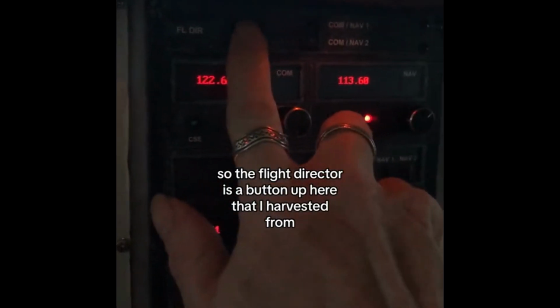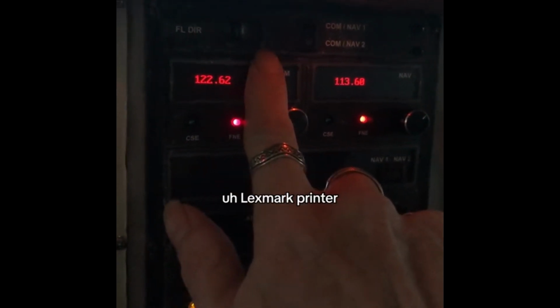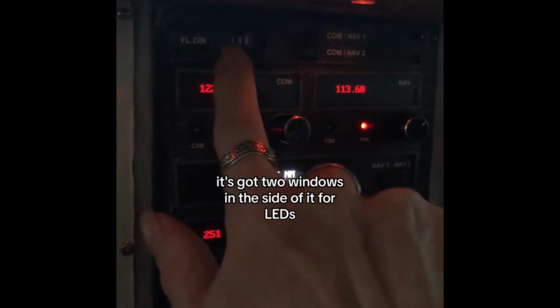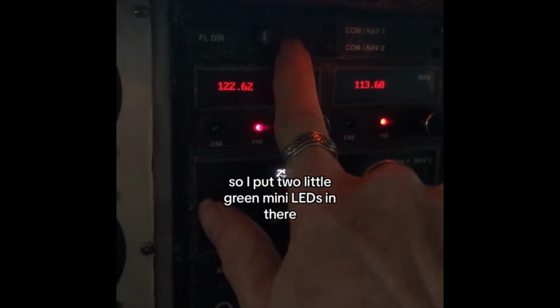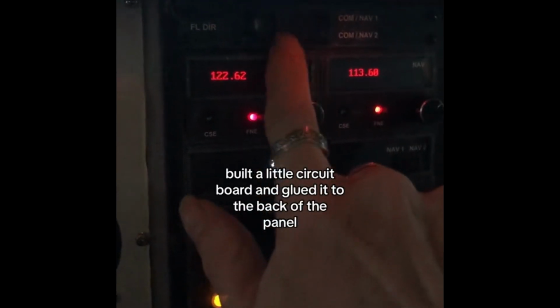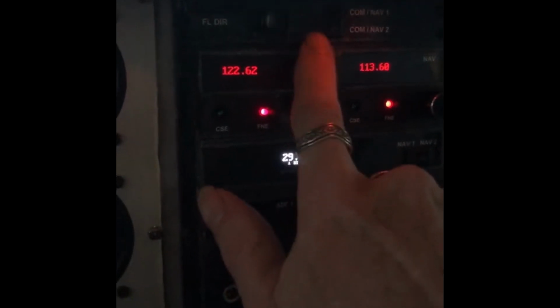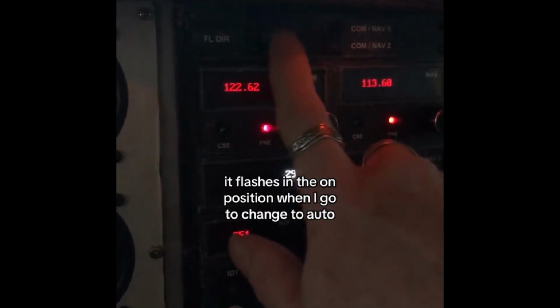I'm going to check out the flight director and the autopilot. So the flight director is a button up here that I harvested from a Lexmark printer. It's got 2 windows in the side of it for LEDs, so I put 2 little green mini LEDs in there, built a little circuit board, and glued it to the back of the panel. It flashes in the on position.